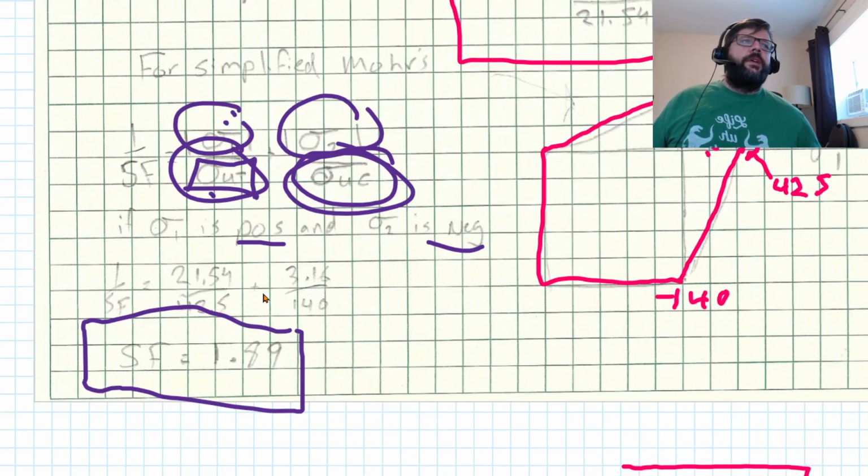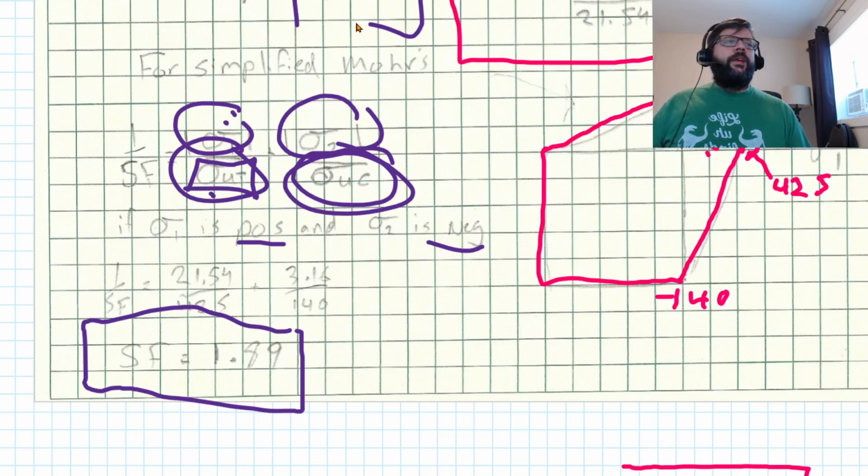So that's slightly lower than what we see with the Rankine theory, and that's accounting for the fact that when you have principal stresses that are different types, like if you have both compressive or both negative, then the largest one is the one that comes into play in Rankine, in modified Mohr's, and any of those.